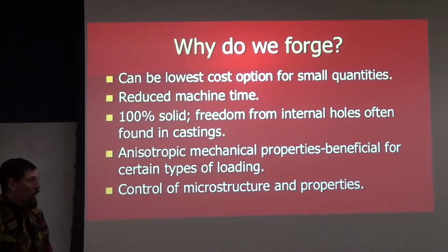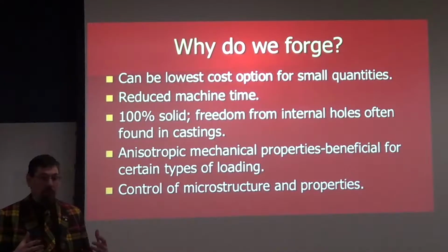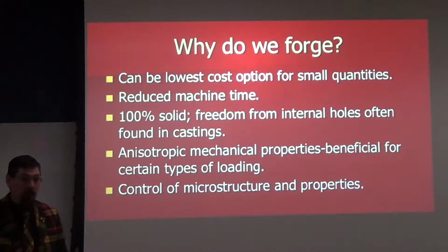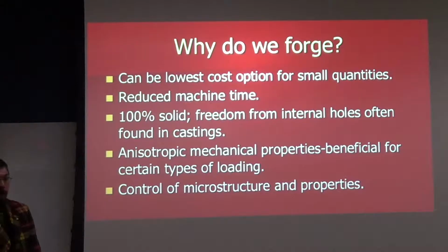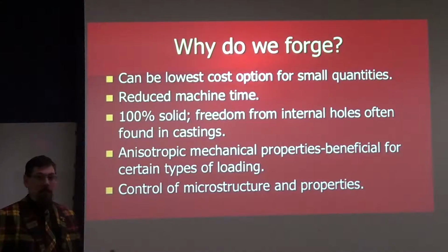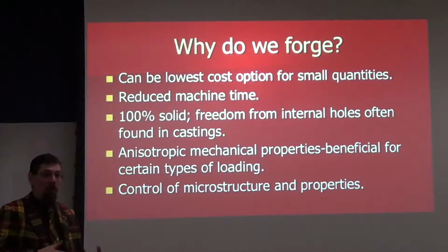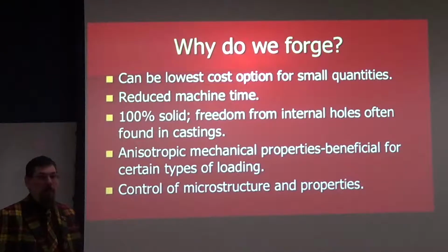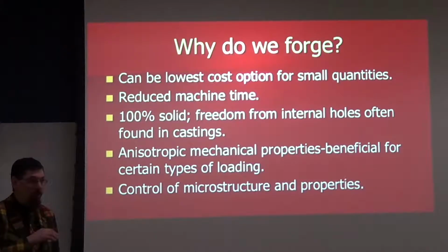Here we have anisotropic mechanical properties. So this is particularly good when you have items that are loaded in fatigue. I showed those axles before for the giant dump trucks. That's a fatigue type application. You've got an empty truck and then a full truck. You've got bumps you go over and maybe a smooth road. That's fatigue. And forgings, because you're able to force the metal to flow around features, will give you enhanced fatigue life.